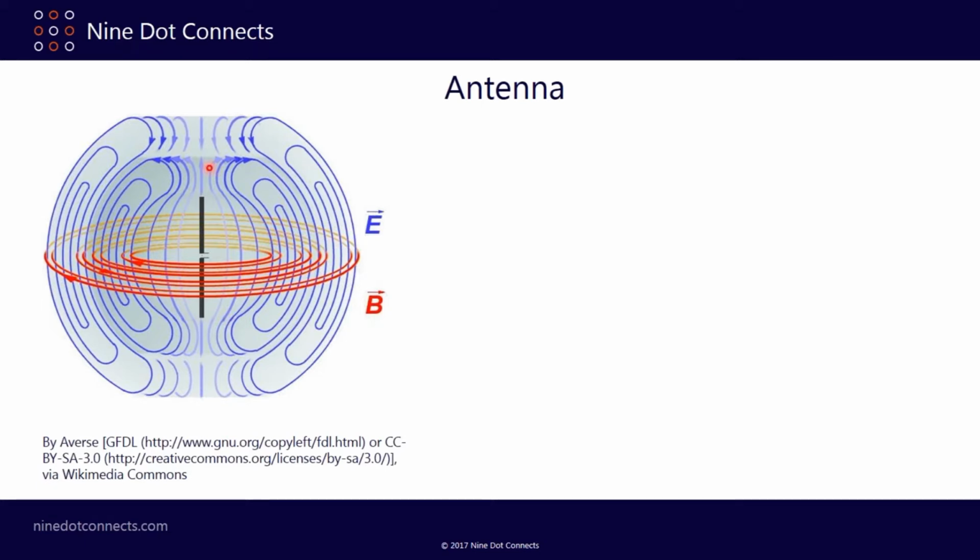But at the same time, because you have a fast slew rate, you're going to have a lot of current trying to move through this inductor. The current going through the conductor creates your magnetic field. So the magnetic field being radiated at the same time as the electric field creates this concept of a TEM wave, or transverse electromagnetic wave, because the E field and the B field are orthogonal or perpendicular to each other.